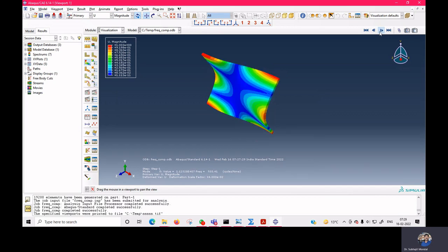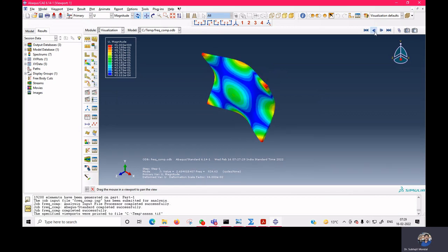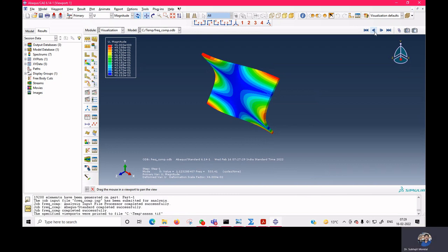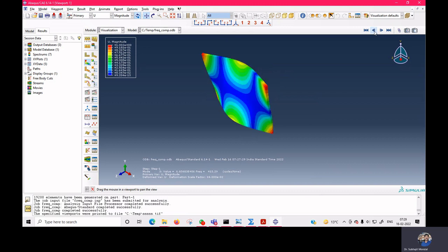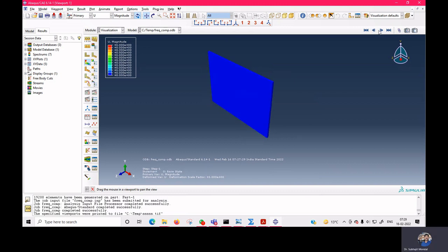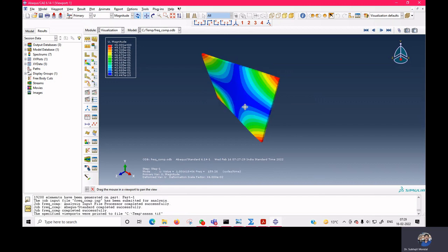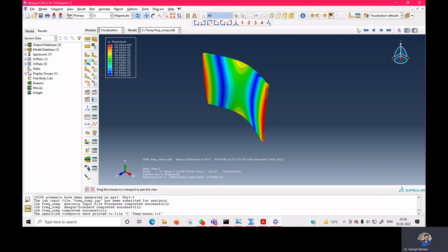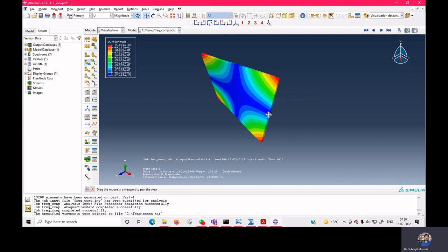So this is the mode shape of the plate. Okay. So now one more thing you have to keep in your mind. Mode shape is the shape indicating the easiest way for a structure to deform. So here you can see for a plate with no boundary conditions, this is the easiest way to deform. So this mode is somehow a twisting type mode. This is the easiest way for the plate to deform. The next easiest way to deform is this shape, a bending shape. Okay. So here you can see that mode shape is also related to the energy, modal energy.